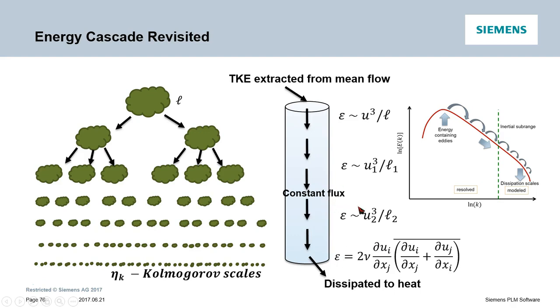So if we cut this energy flux pipe at some intermediate point and provide a proper dustbin for the energy flux, then perhaps the larger scales will not even notice the absence of smaller scales. And that is the primary goal of the subgrid stress models, to dissipate the correct amount of energy transferred from the larger scales. And in a well-resolved LES, the boundary between the resolved and unresolved scales is situated in the inertial subrange.